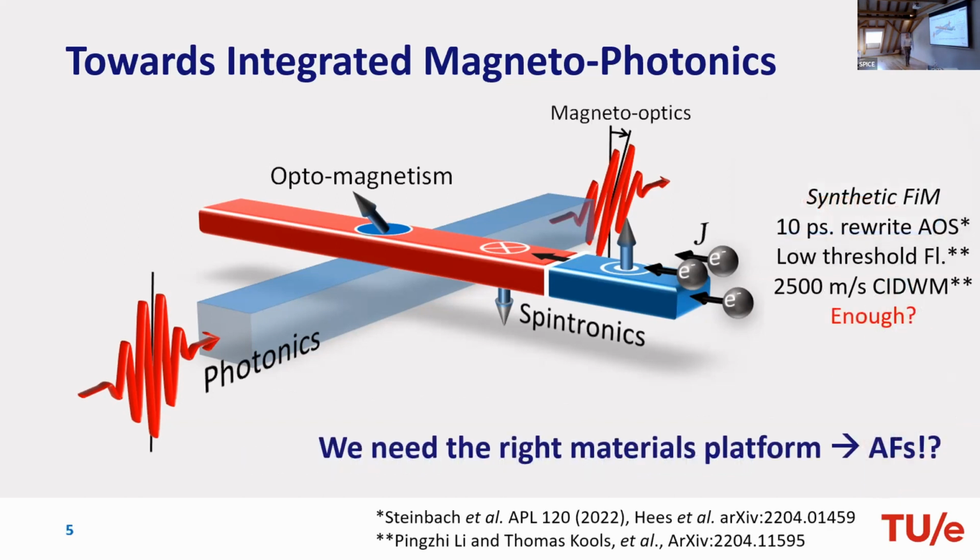So what is the current state of the art? If you think about the materials here, the photonics is all well defined. So integrated photonics already works at these high rates. The stuff on top, the magnetics, so if you look at synthetic ferrimagnets, so for instance, the materials that Stuart Parkin has introduced, etc., domain walls flying through at 2.5 kilometers up to 5 kilometers per second is proven. That's state of the art at the moment, right?